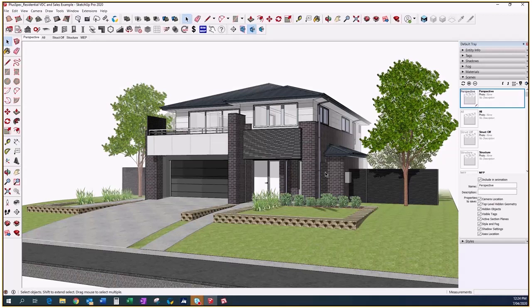Whereas virtual design and construction is taking it to the next level. It's saying that there is going to be frame, there's going to be steel, there's going to be MEP, and there's going to be finished materials shown inside of the model. And the benefit is that you can understand clashes, mistakes, errors, and more importantly, that you can communicate to every single person that needs to build that project in the right way.